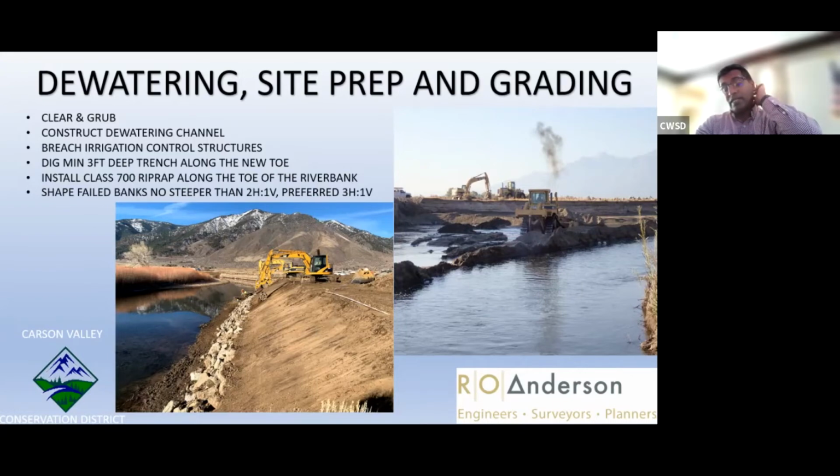For instance, there's one project where, when we first started designing it, everything was just fine. We thought we could do 3-to-1. But then as the project progressed, the landowner wanted to build this big barn, and right next to the river he had a fiber optics line, a new road, and underground electric very next to the river bank. So if we were to go 3-to-1, at 12 feet or 15 feet, we're cutting back about 30 to 40 feet. We'll just take away his newly put in road and other utilities. So we had to adjust a little bit in the field.